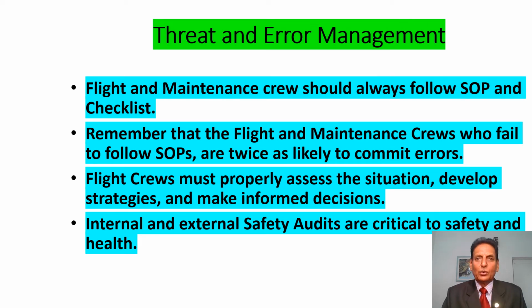Flight and maintenance crew should always follow SOP and checklist. Remember that the flight and maintenance crews who fail to follow SOPs are twice as likely to commit errors. Flight crews must properly assess the situation, develop strategies, and make informed decisions. Internal and external safety audits are critical to safety and health.